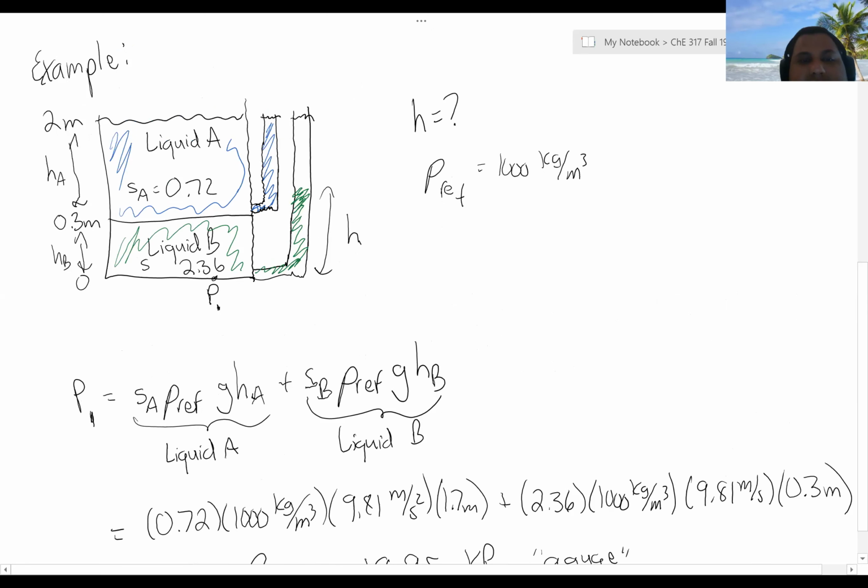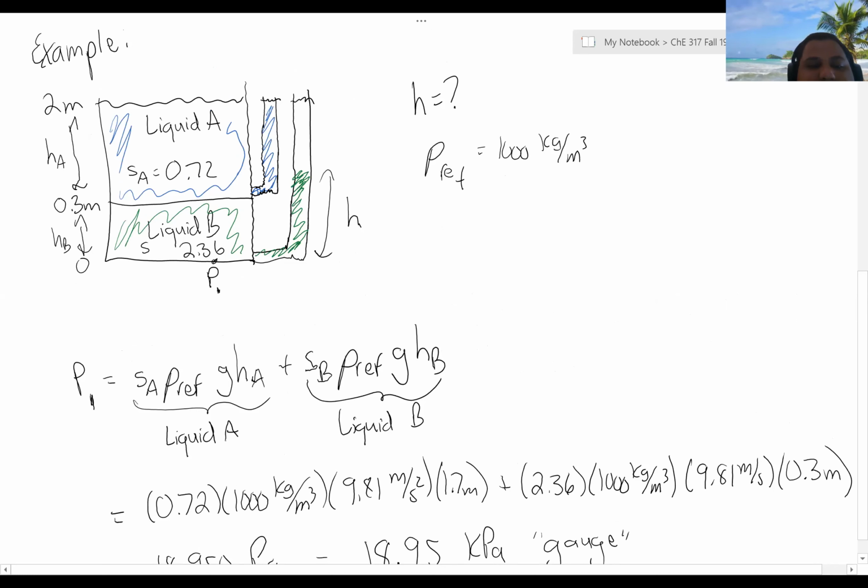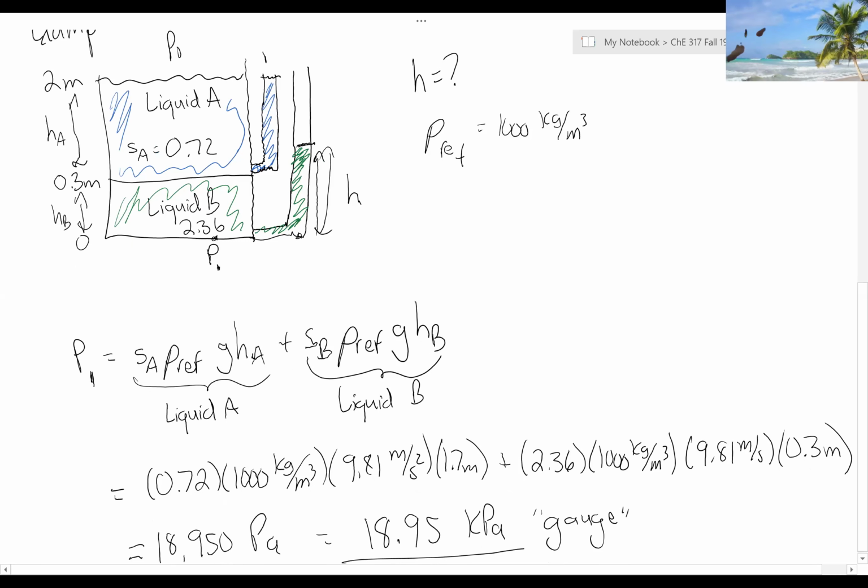So that's the gauge pressure. Because we don't know the pressure at the top of this column, if we use things in terms of gauge, it doesn't matter. We can get the pressure at the bottom of the liquid column. And so knowing that pressure and that this system is in equilibrium, we can say the pressure as it moves up in height decreases, and at the top of that liquid level, assuming these are all open to the same container or atmosphere, these should all be the same, which means if this is P naught, this is also P naught, and then the top over here is P naught as well.